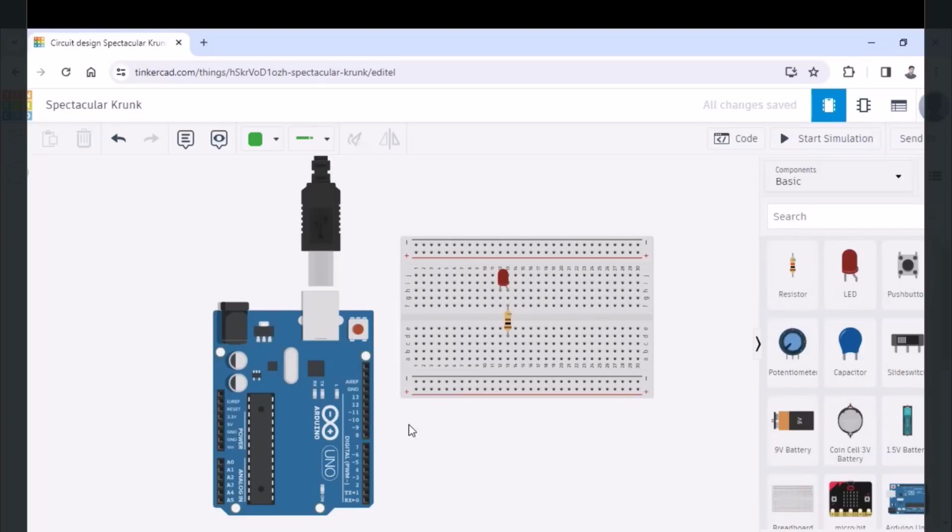Let the components be like that only, and I know that I need to apply the power, so I'm doing like this, and then I'm giving the input to this. Okay, what I'm doing is, pin number 8 is my input terminal, which I'm going to connect from this. So I will connect like this. So here in all the pins, 8 number input will be given. So I will connect this resistor somewhere, this to this.